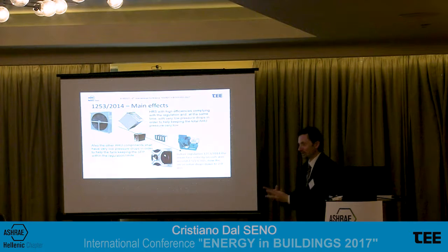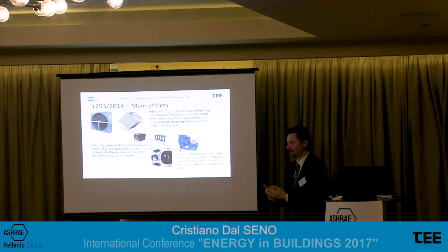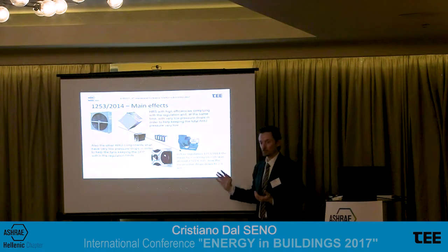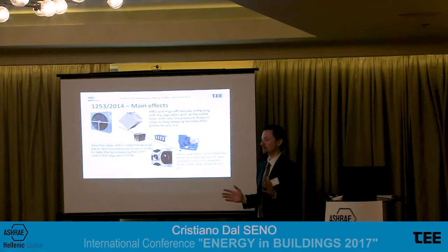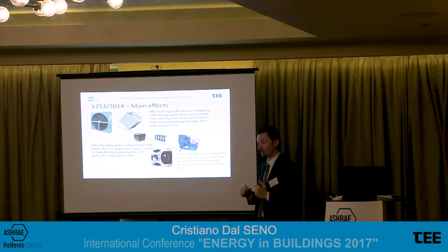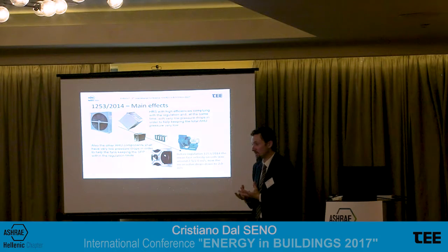But generally talking, to give you some easy information, what are the consequences of the application of this norm? According to our experience, the main subject is wheel and plate recuperators. There's no way. If you want to achieve compliance with the eco-design, we must design larger plate exchangers or larger wheels in order to boost the efficiency and at the same time reduce the pressure drop. Because these systems are anyway the most important systems inside the unit.